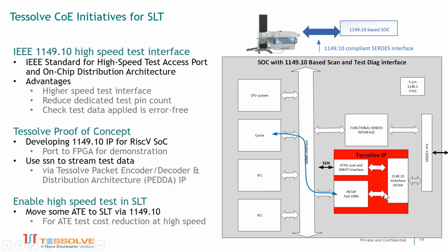I don't know about whether it's suitable for a bunch of wires, but certainly for UCIe, if that's sat behind a high-speed SerDes, we could potentially use that in the final package chip. So chips could be talking to each other along a high-speed interface, and then we could do a lot more structural testing. One of the chiplets could be a master chiplet that's feeding structural tests to those IPs that are in situ.